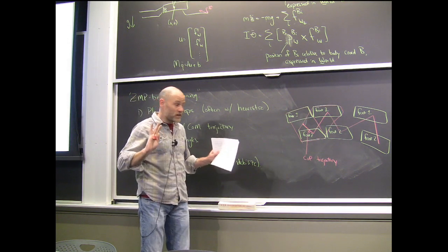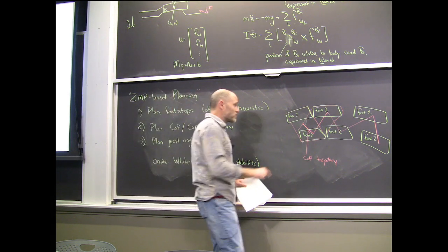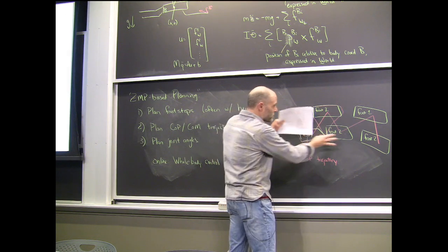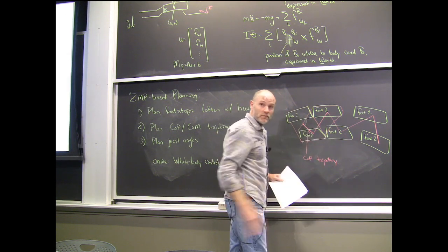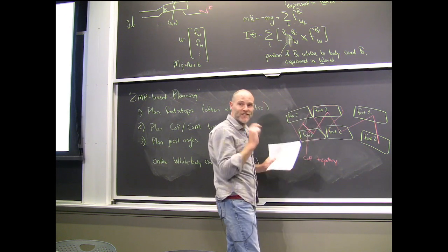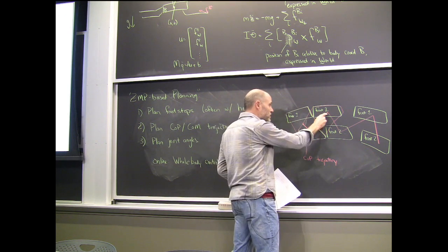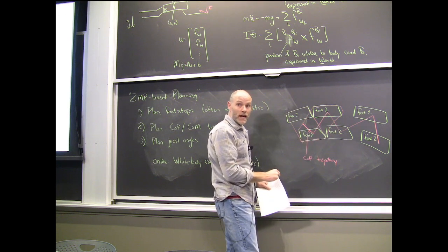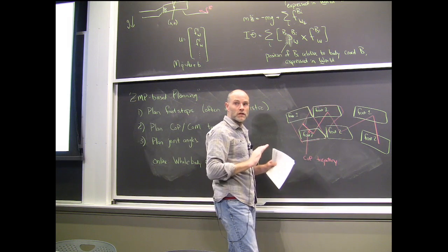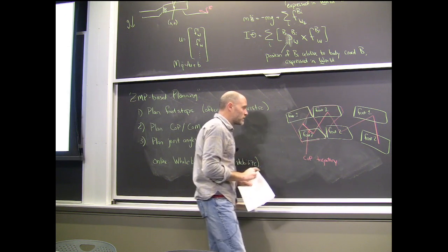But the simplest version of this: someone just gives me my footstep planner. I could imagine a very simple heuristic for laying them out on the path to the goal. And I will hand design a ZMP trajectory that just goes near the middle of the foot at a certain timing. Straight lines, piecewise linear interpolation, no optimization. You can get fancier.